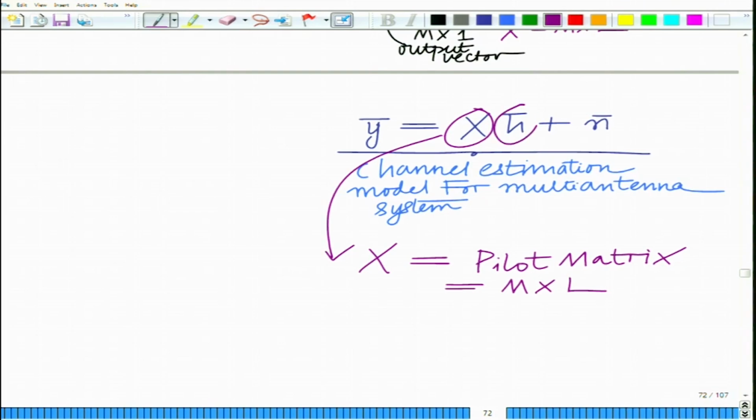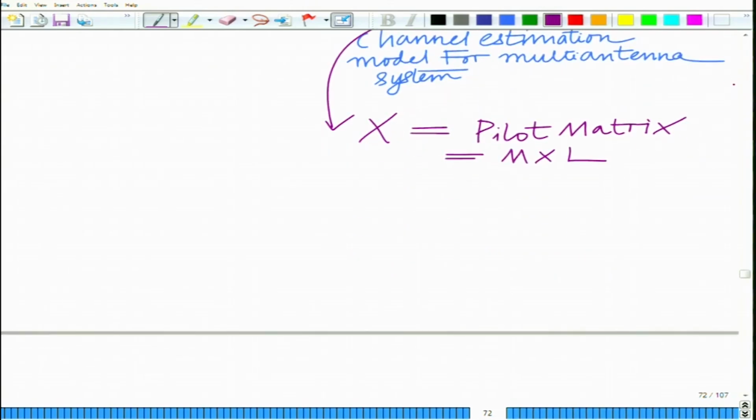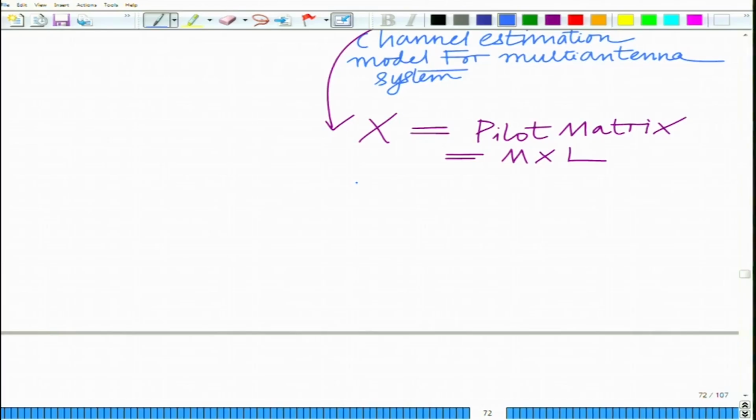And this vector h bar, remember this is the CSI, this is unknown. This vector h bar which represents the CSI is unknown, and to estimate this h bar, remember, of course there is noise, this is the noisy observation model. So, you have to look at the best vector h bar which explains the observed vector y bar corresponding to the transmitted pilot symbols in the matrix X. So, therefore, now one can formulate the estimation of h.